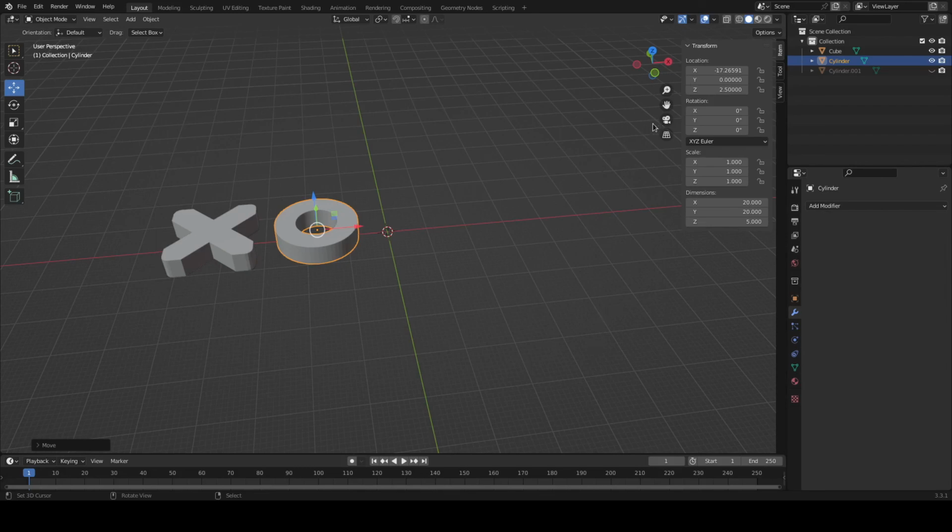So now that you've got Selection Only checked off, we need to make sure that we are saving it to a place where we'll be able to find it. So let's come over here. We want to save it to the desktop. So here in the system panel is desktop, and you can see that right now it's going to be called untitled.stl. So I'm going to click on it, and I had my O selected, so I'm just going to put the letter O, and I don't actually need to type .stl. When I click off to the side, the system will add .stl for me. So now I'm adding o.stl to my desktop. So here we are, export.